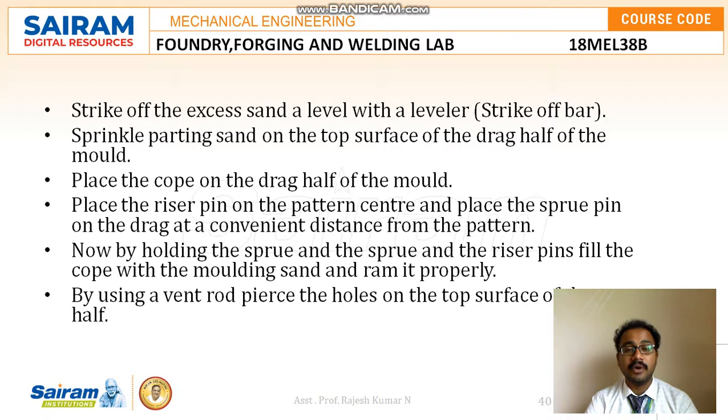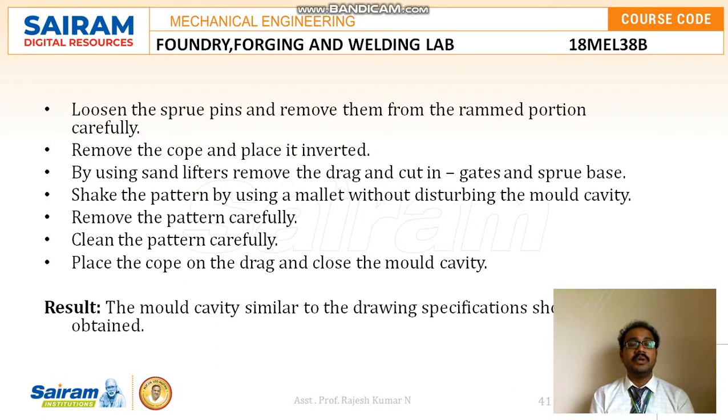By using a vent rod we need to pierce holes on the top surface of the cope half. Later, loosen the sprue pins and remove them from the rammed portions carefully.